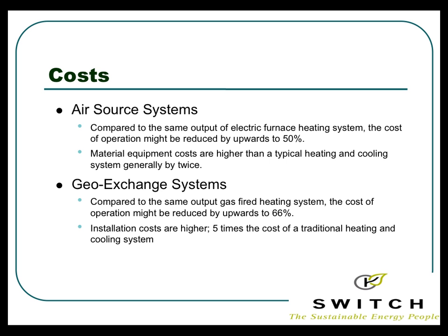Air source heat pumps are now able to, with inverter technology, it allows for variable speed compressors and variable speed outdoor fans, we can run down to minus 30 degrees. Okay? Whereas before we wouldn't necessarily run below freezing, below zero. Okay? But new technologies allow us to utilize air source heat pumps. Costs are typically about twice the cost of putting in your normal furnace and air conditioning system.